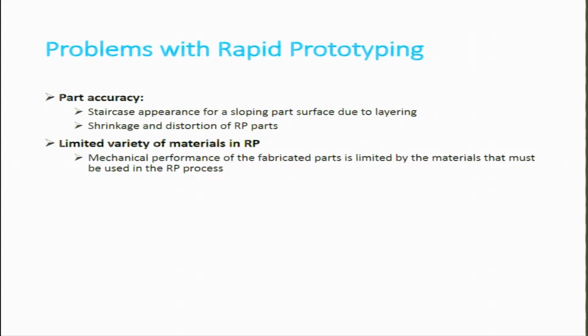There are certain problems as well with such rapid prototyping techniques, particularly the FDM process techniques. So, one of them is part accuracy. Obviously, when we talk about zooming close to a part, you will always find a staircase type orientation, and you can see differences between the layers. There is no reflow mechanism between layer 1 and layer 2. For example, if you have printed something in layer 1 and then another in layer 2, these are like pyramidal in nature. Okay, so the staircase orientation actually comes up as the FDM process goes up. Had there been a reflow option where they would have slightly leveled off, it would really have changed quite a bit of surface properties, okay, associated with